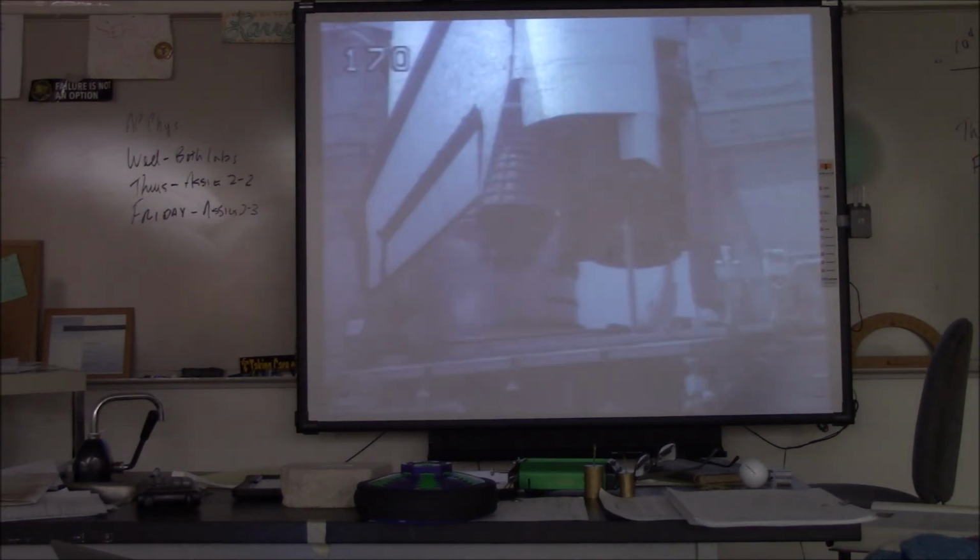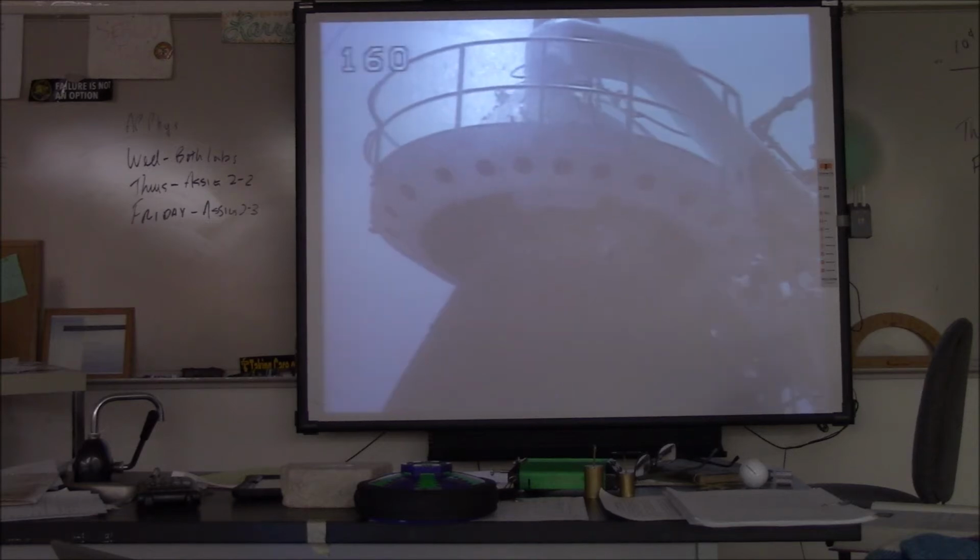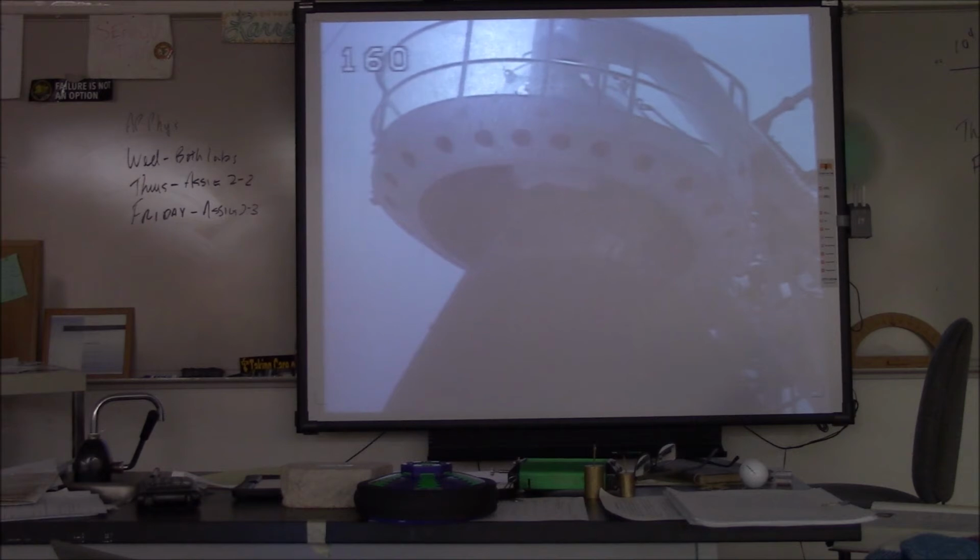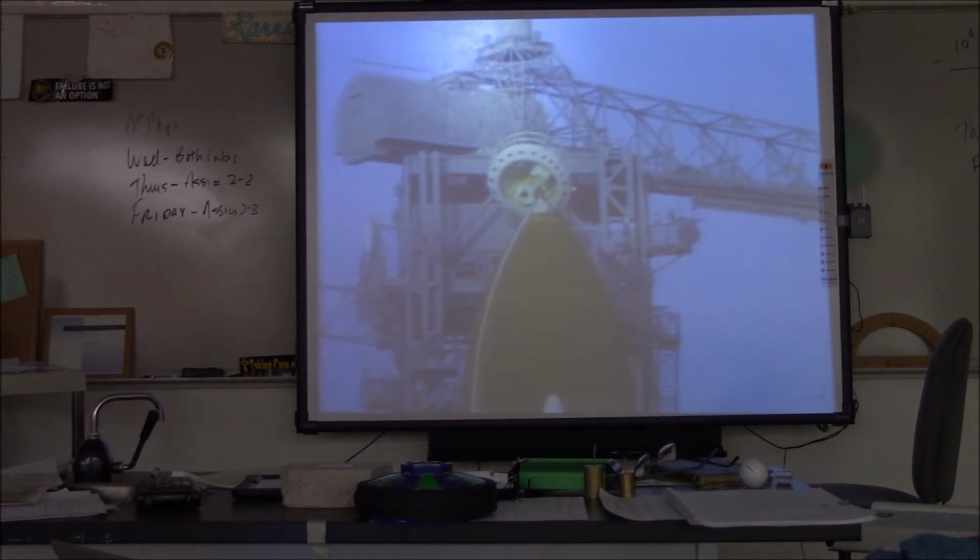At 3 minutes before liftoff, the main engines are swiveled to their proper launch positions. All of the shuttle's engines are mounted on a pivot device, or gimbal, which allows the flow of exhaust gases and the direction of thrust to be controlled during ascent. The oxygen and hydrogen vent arms retract at just 2 minutes before engine ignition.